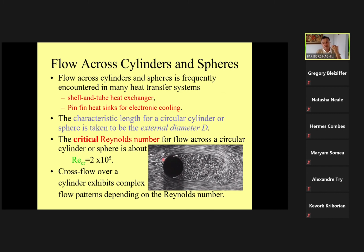If the flow is very laminar, at very low velocity, the fluid comes here, touches the pipe, and slowly moves back here. As we increase the velocity, separation takes place. As this separation takes place, the fluid jumps over here and creates some recirculation. That means a fluid going in this direction is going back in this direction. Depending on this, we expect the heat transfer to be different.